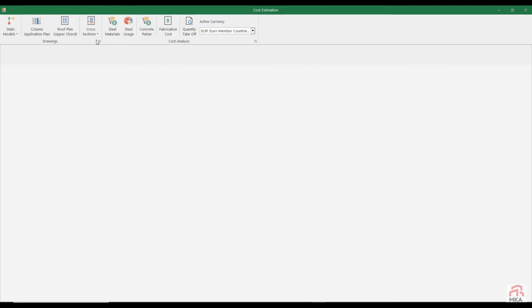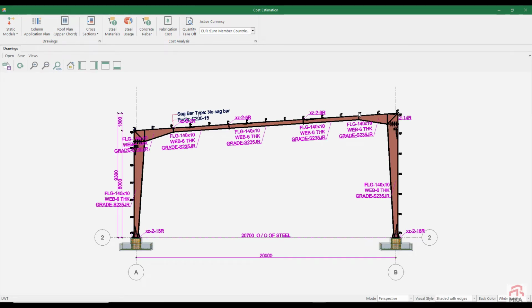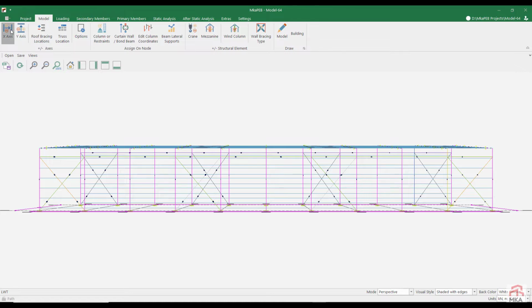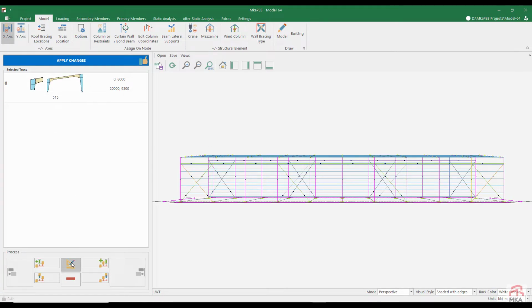Let's look at the shape of the building. Is there any place that bothers the eye? It would have been better if one or two more purlins continued here. Maybe we could make it a little lighter then. 26 kilograms is pretty good for a building of this type, but let's try to get even lower, shall we? For this, I first increase the following from the model section.